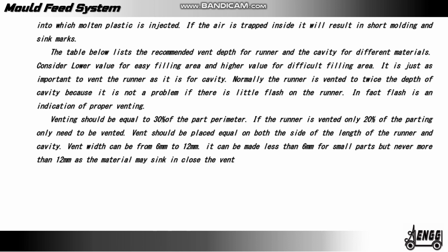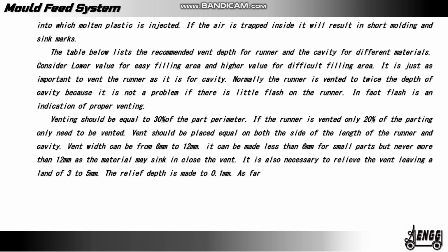It is also necessary to relieve the vent, leaving a land of 3 to 5 mm. The relief depth is made to 0.1 mm. As far as possible, the vent should be ground.